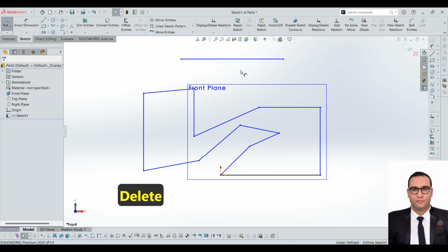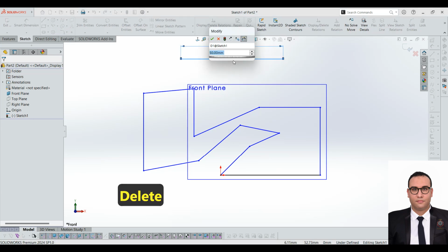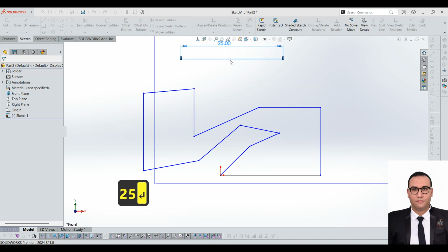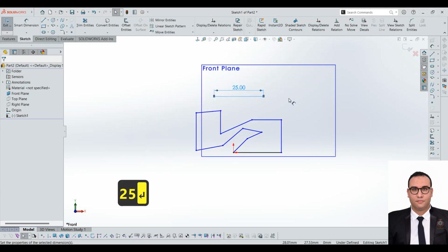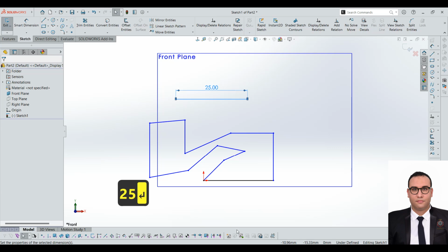If we delete it and do it again by clicking two times, it appears here, 125, and the sketch will become smaller. It will auto scale the entire sketch. So you have to be very alert. It is very important, because if you begin with a very small sketch, you can't do the trim. You have to choose exactly the one to begin with, as you see.